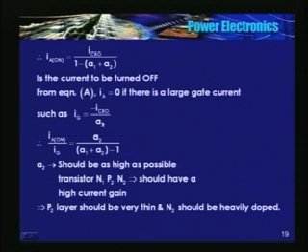Okay. So if I want to find out the gain or the relationship between the anode current and the gate current, it comes something like this. IA divided by Ig is equal to alpha 2 divided by (alpha 1 plus alpha 2 minus 1). How do I improve this gain? In other words, how do I make this gain as high as possible? Alpha 2 should be as high as possible.